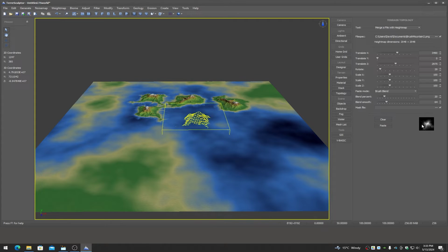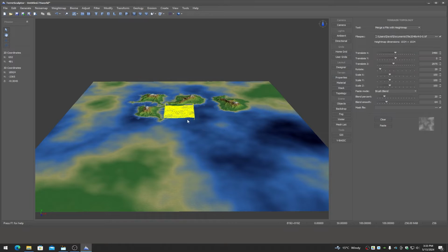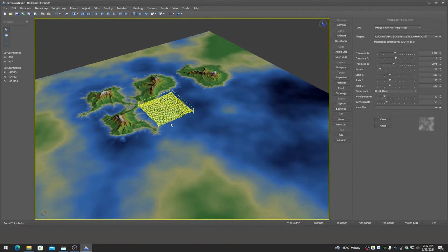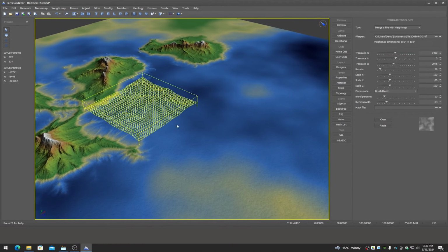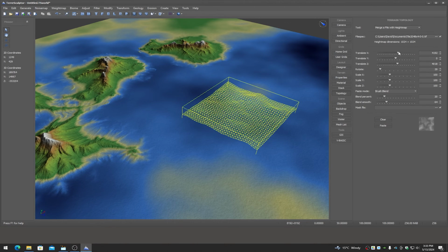And of course here in the preview I can see a preview of the brush that I'm working at. And this gives me information on it, tells me it's a 2048 by 2048 brush. If I actually bring in a tile that's not a brush, you can see I now have a tile that I've brought in. And what I would want to do with that is not use the brush blend. I would want to use something like the circle blend to blend that in.